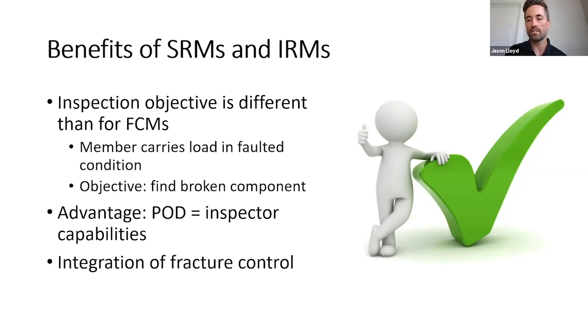In addition, we're now integrating the quality of materials, quality of fabrication, and damage tolerance with the inspection interval. So this really is the first step in truly integrating the fracture control plan using rational risk-based inspection intervals. In other words, the inspection depth and interval become tailored to the bridge or the member in question. It's no longer a one-size-fits-all.